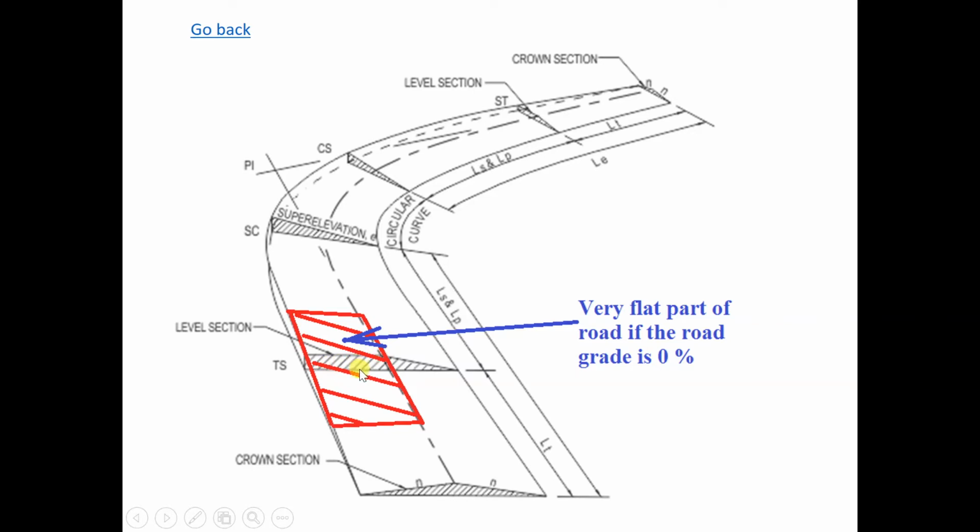Especially if it's a multi-lane dual carriageway, with one side having three lanes, it could be a drainage problem. And also the inside here is flat road as well, so water may accumulate at the inside of the curve here.